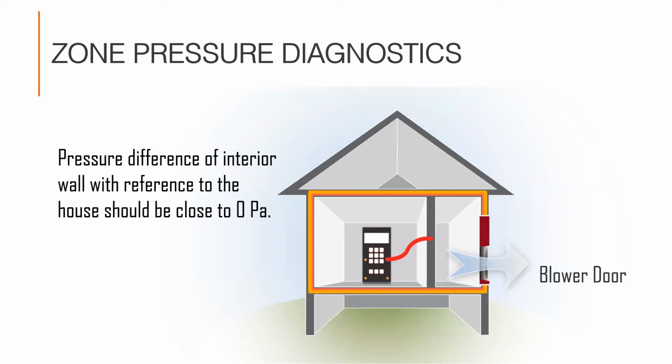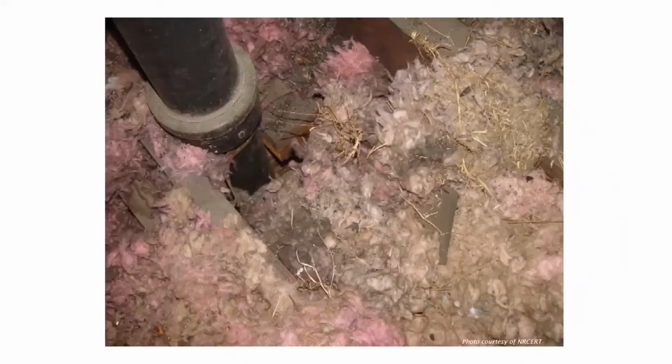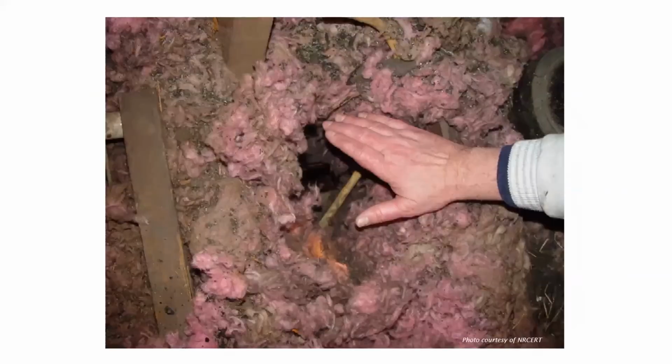When you probe interior walls and other interstitial cavities, there should be zero difference if they're truly inside the air barrier. Small or large deficiencies indicate the presence of or severity of breaches in the air barrier. Plumbing chases often create breaks in the air barrier. Not only do penetrations like these increase a home's air leakage, they also reduce the R values in the nearby attic insulation.